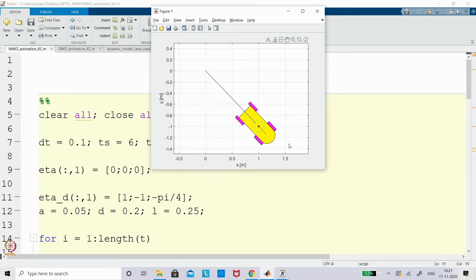But the same situation may not be applicable to certain vehicles, right. A very simple example: if you take a unicycle, a differential wheel drive, or a tricycle, these will not be eligible. Why? Because these mobile robots are called non-holonomic, in the sense that not all 3 states can be achieved, only certain states would be achievable. That is what we are going to see in the slide.